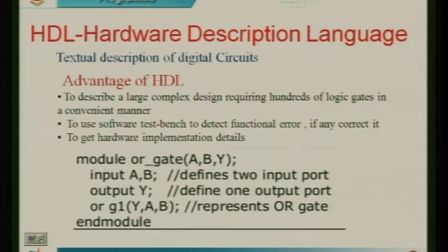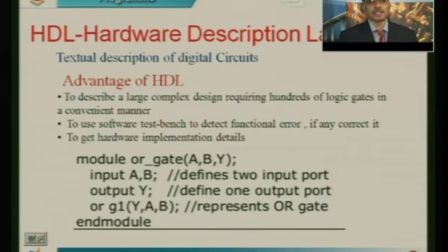The major advantage of using an HDL language is that it can be utilized to describe any complex circuitry in a simple manner. Another advantage is that the software we use to describe the behavior of a digital circuit supports writing a test bench, which is used to generate and test waveforms that can be given to the model you have written, to see whether the functionality is working correctly.